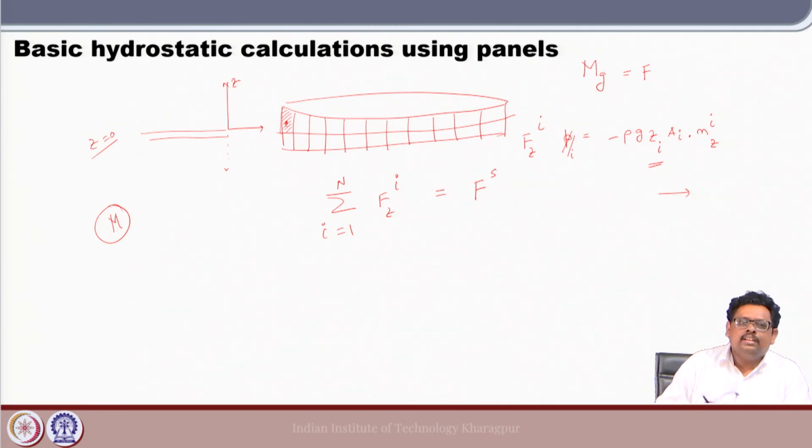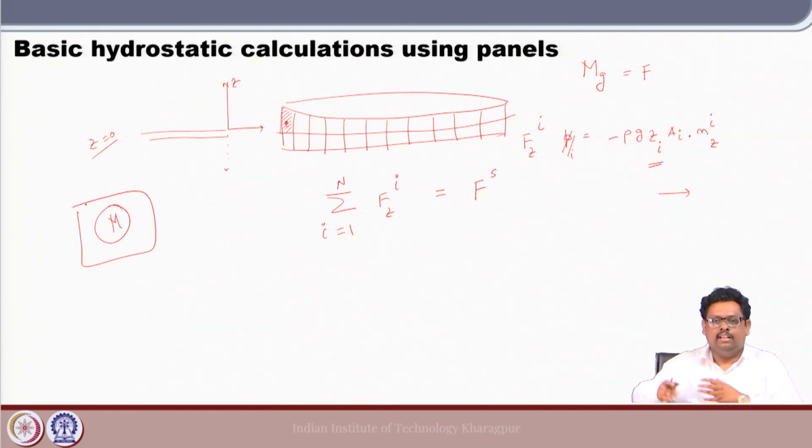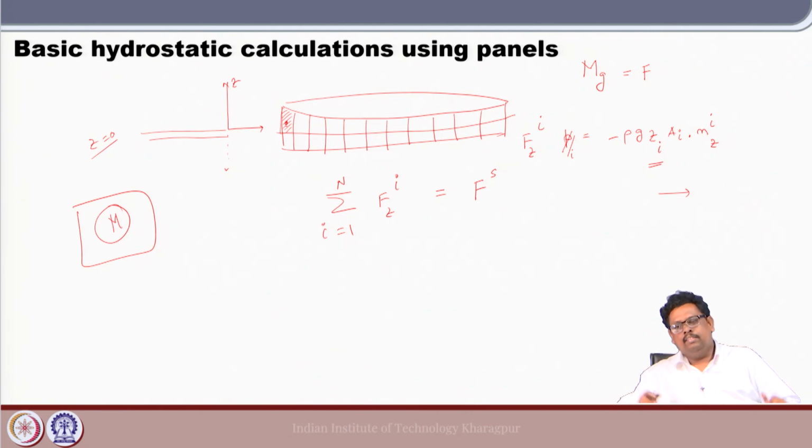You go with the convention that I should take this mass, a little bit conservative on this hydrostatic part. And then you say, okay, this is my ship, this is the design. So I must take this m which is given to me from the hydrostatic table or the design office. When they calculate the hydrostatics, they give you this mass, and you say that no, I am going with this mass. However, when you do the paneling, it might not be that great.